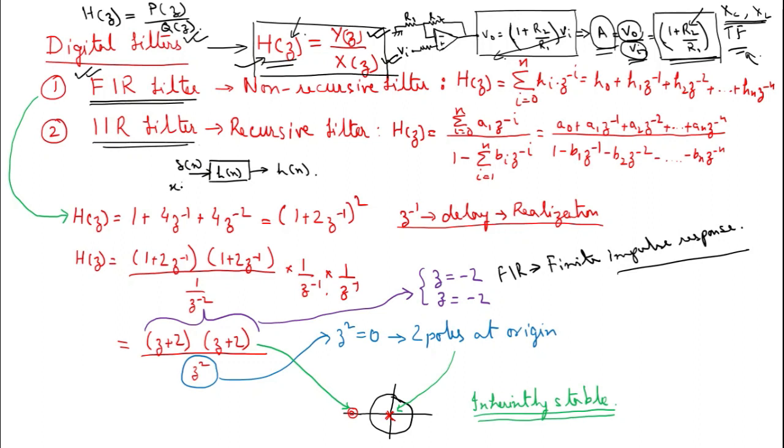So we give x(n), we get y(n), which is equal to x(n) convolved with h(n). This is the basic formula for the output of a given LTI system. Now, in this LTI system, if we give an impulse input, that is, at n equals 0 we have an impulse, and at all other time instances we have 0 amplitude, then the output we get is the impulse response.